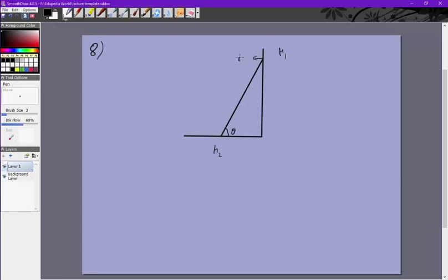There's a normal force acting here, N1, a frictional force acting upwards, which we'll just write straight away as mu1 N1 because it's the limiting case. There's a normal force here, N2, and a frictional force towards the right, mu2 N2, and of course there's a gravitational force acting at the center, mg. And this angle is theta, so this is 90 minus theta, so this is theta.